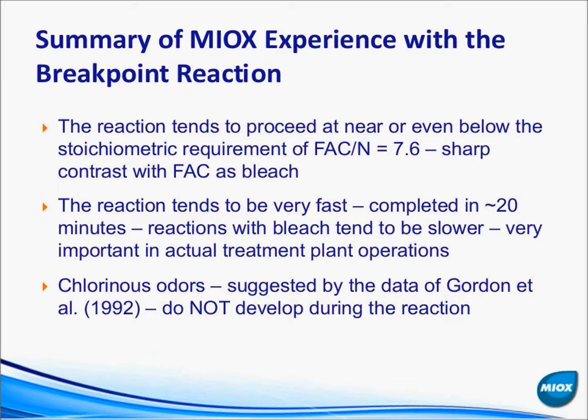In actual treatment plant operations, this means that you're usually able to see the effect of it in the plant itself, as opposed to having to do further and further tests, or testing further and further downstream in your distribution system where the reaction continues to take place. And finally, if you go all the way through to breakpoint chlorination, the chlorinous odors can be greatly reduced. One thing that you also might be familiar with is that incomplete reaction of the ammonia, or even reaction of ammonia with bleach, can produce that real swimming pool-y smell. We tend to drive that reaction further to completion, and as a result, tend not to get a lot of the side product formation, and the chlorinous odors are greatly reduced as well.